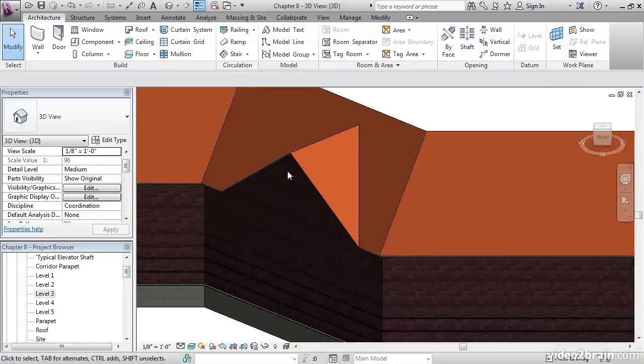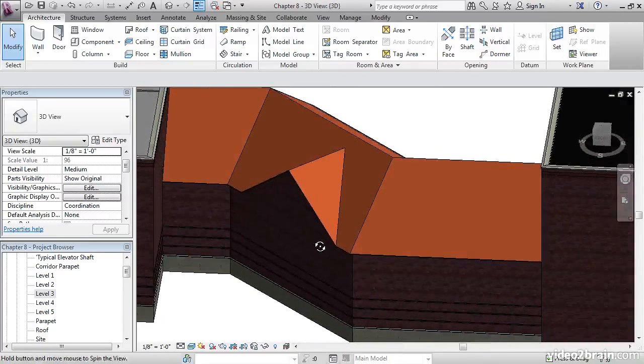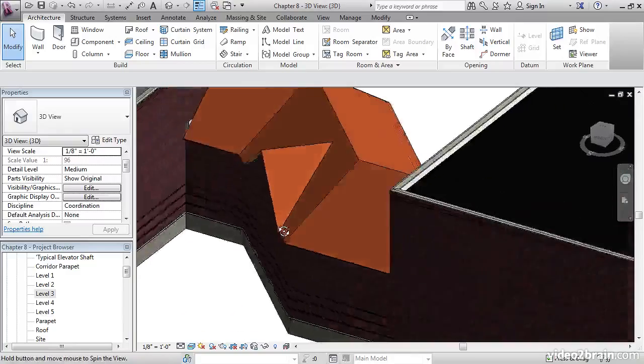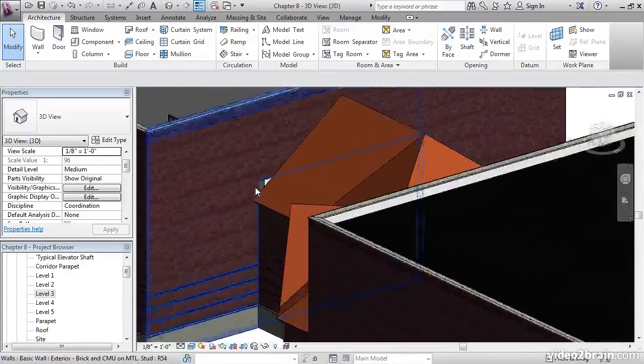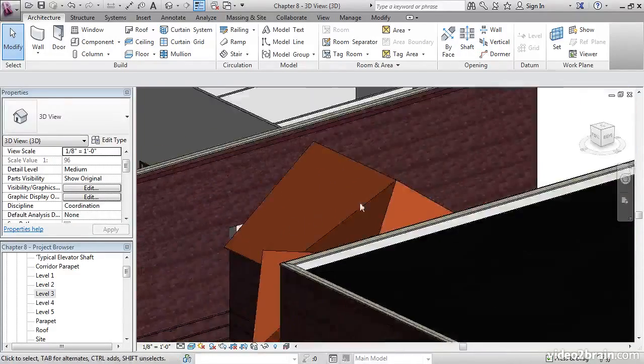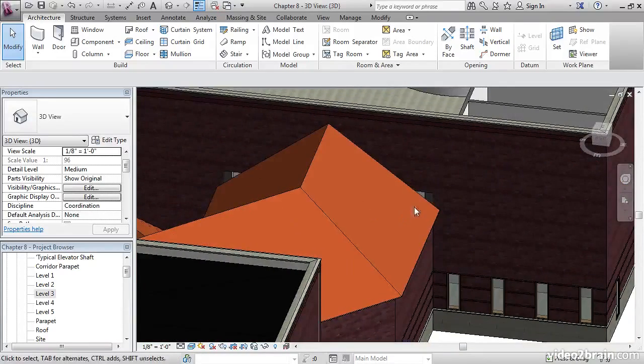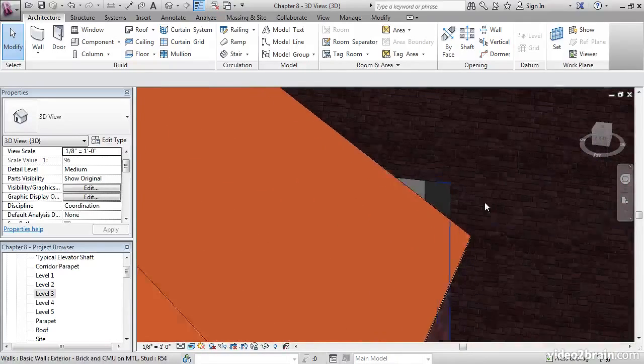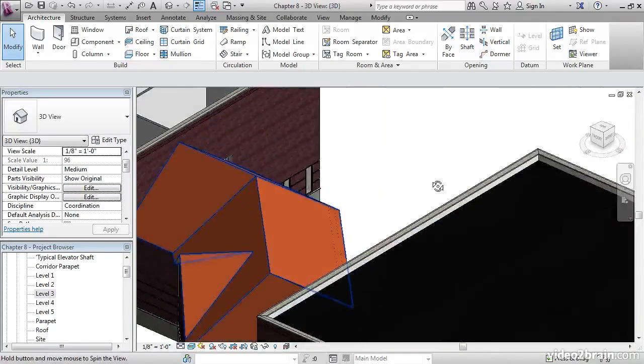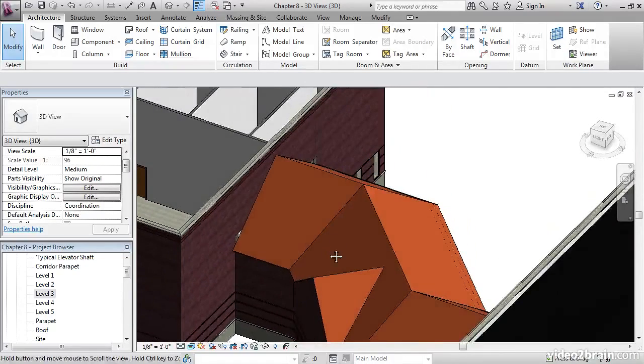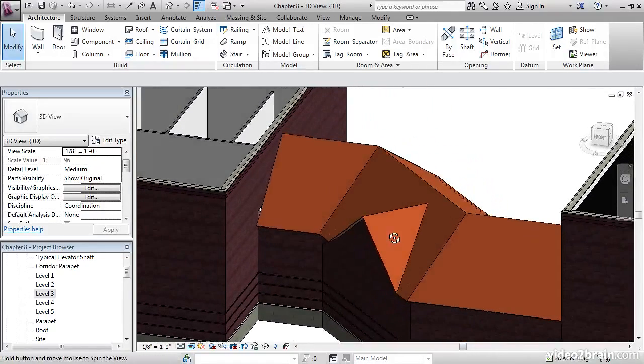How did Revit know to attach the wall to it? We told it to attach the wall before. This wall is attached to the roof. One thing to look at, however, are these horrible gaps in the wall. Well, I always maintain I'm all about precision, and I had you leave some big holes in the wall. I'm not going to lie, I kind of did it on purpose, just to bring up a point.